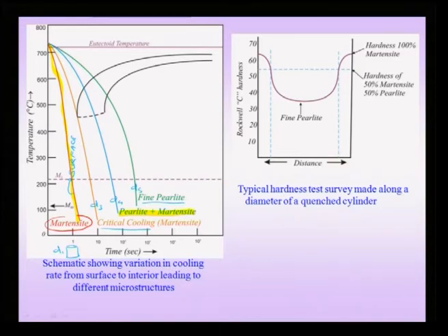a thick specimen. For instance, the surface could be feeling a very high cooling rate, while some point in the interior could be feeling, for instance, just the critical cooling rate, in which you will form 50% martensite, or somewhere deeper in the material you will just get fine pearlite. That means there is a microstructure variation within the sample while you are quenching the sample, and that means that we have to be a little careful that whenever we dealt with CCT diagrams, we had talked about quenching and producing martensite. What essentially we were talking was that the sample surface is forming martensite, not the entire sample.